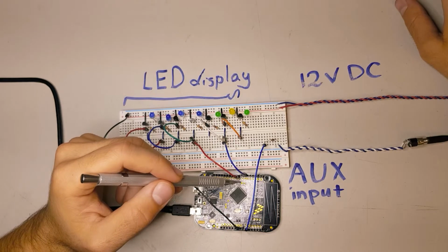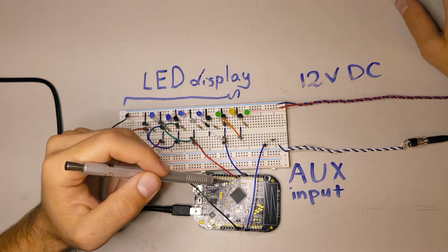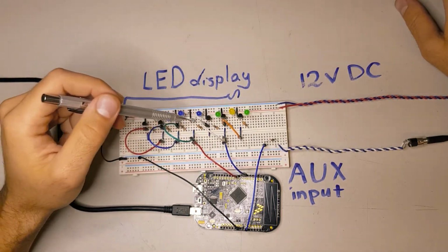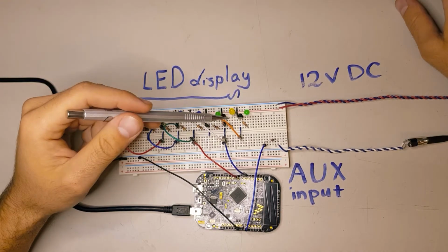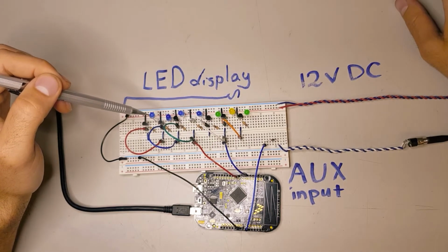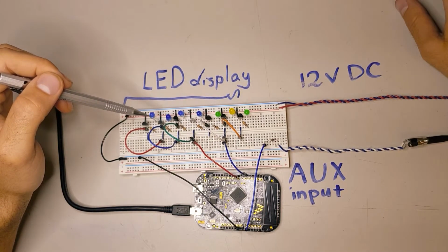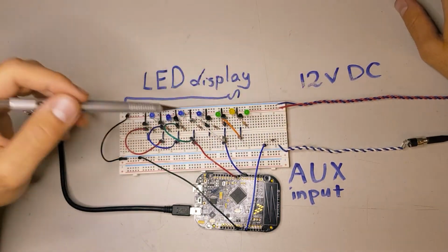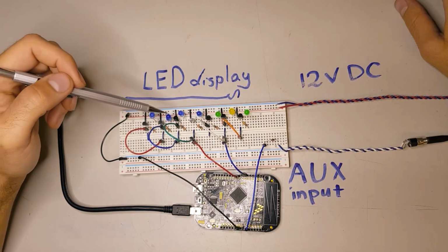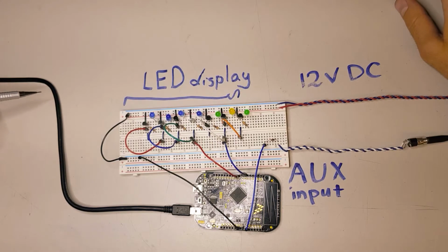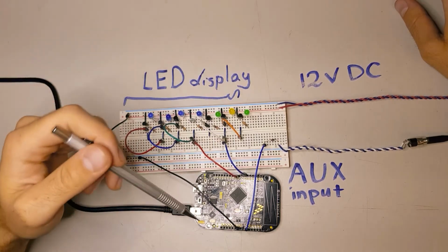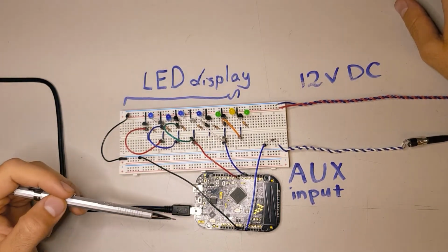PTA13 for low pass digital out and PTA5 for high pass digital out were jumped to the base of one of those transistors that were used as switches to power one of those LEDs that were later switched to LED strips for the actual display. 12 volt DC was inputted across the positive and negative buses to be able to power the LEDs. The mbed was powered separately because 12 volts would damage the mbed circuit.